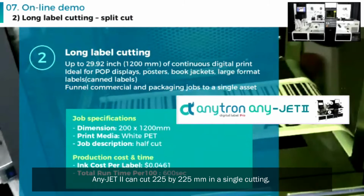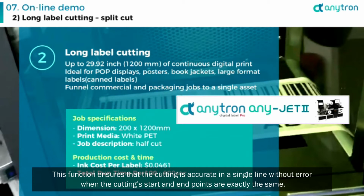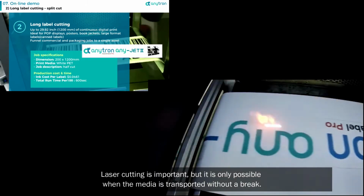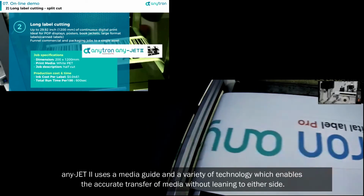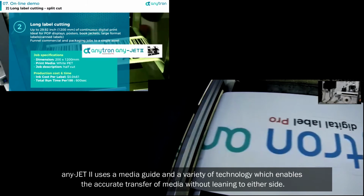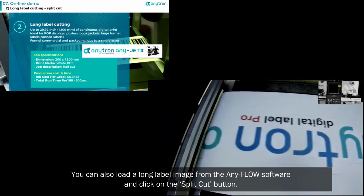AnyJet 2 can cut 225 by 225 mm in a single cutting, but if you use the split cut function, you can cut labels lengthwise. The split cutting function allows the laser to cut at the cutting's endpoint without cutting the long label at once. This function ensures that the cutting is accurate in a single line without error when the cutting's start and end points are exactly the same. Laser cutting is important, but it is only possible when the media is transported without a break. AnyJet 2 uses a media guide and a variety of technology which enables the accurate transfer of media without leaning to either side. You can also load a long label image from the AnyFlow software and click on the split cut button.